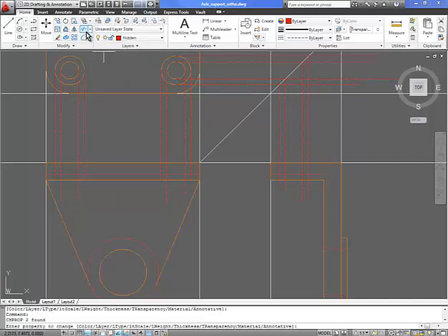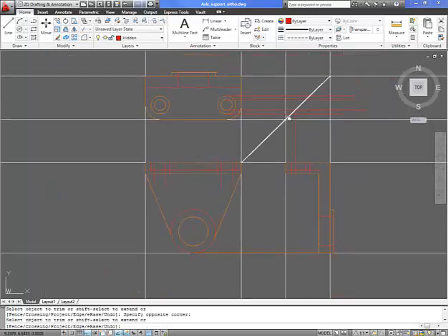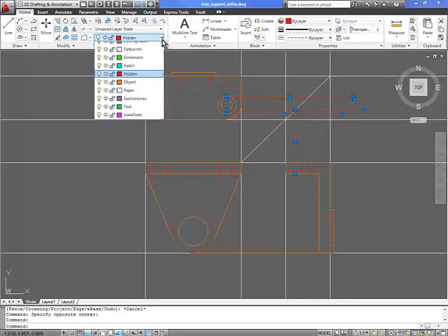Now we're going to go to the trim tool, and we're going to select these lines to be the trimmers. So get everything clean. So all those lines go, these lines go. Same thing with these. We could have used construction lines for these, by the way.